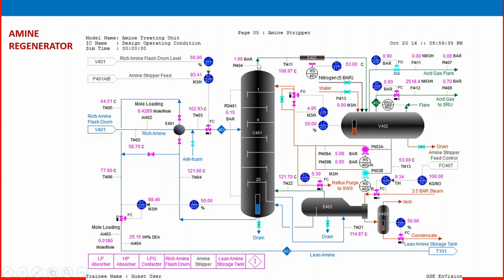So only H2S can escape from the stripper outlet. Slight water carryover will be there. The amine should stay inside the vessel. In this area, a slight condensation cools the temperature, so the amine stays inside to keep amine loss to a minimum. Here a condenser cools it to separate any water, amine and H2S.